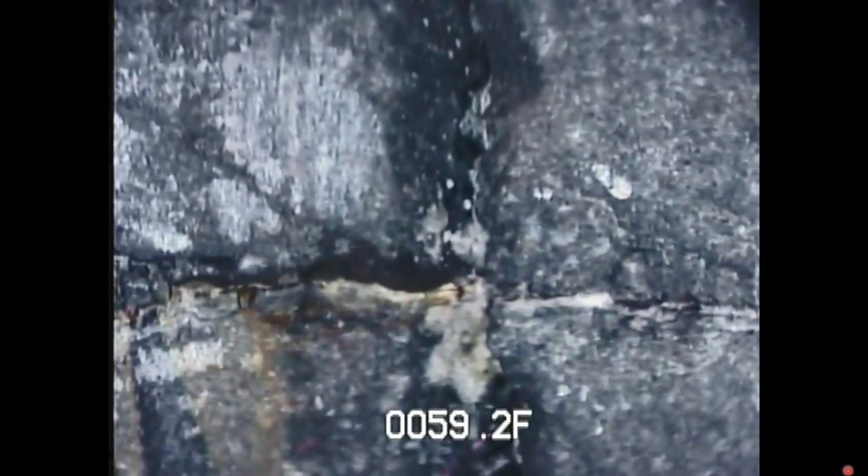And so taking our core log that we talked about earlier, we can zero in on some of these features. Looking at this particular interval at 59.2 feet below grade, just one of those features I was talking about before, we can see some indication of transport and precipitation within this interval. And coming back in with pumping tests as well as actual induced flow, trying to inject material within this interval, tells us that this is actually a high producing zone or a large contributor based on contaminant mass and connection with surrounding features across the site.